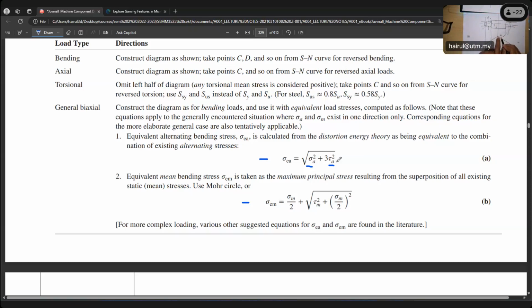So you have to go like this because since you know your moment from your moment diagram, you can find your moment from shear diagram, moment diagram. You can use the Pythagorean theorem to get this moment at this shoulder and the moment at this groove. Understand? You need to find this. So you need to analyze on it. Because this is critical. Why is this critical? Because we have a notch.